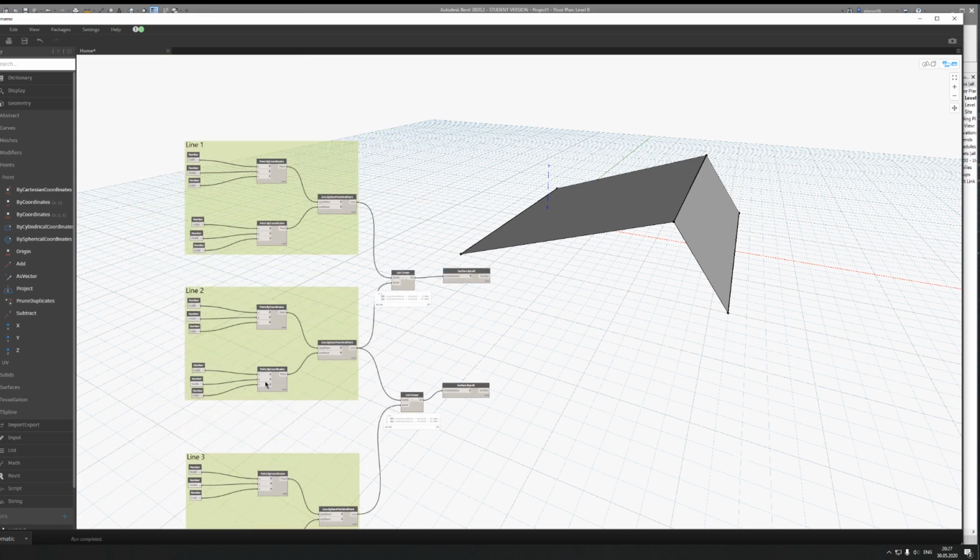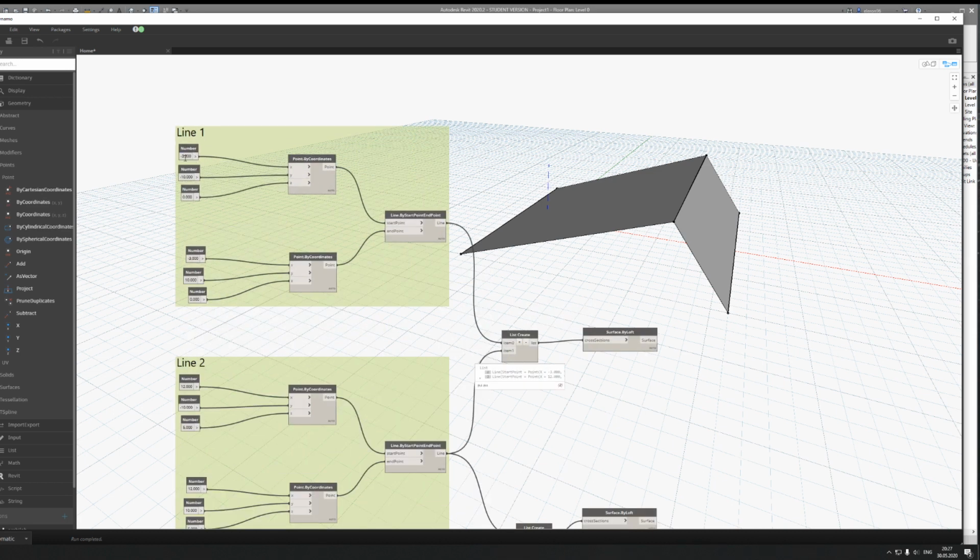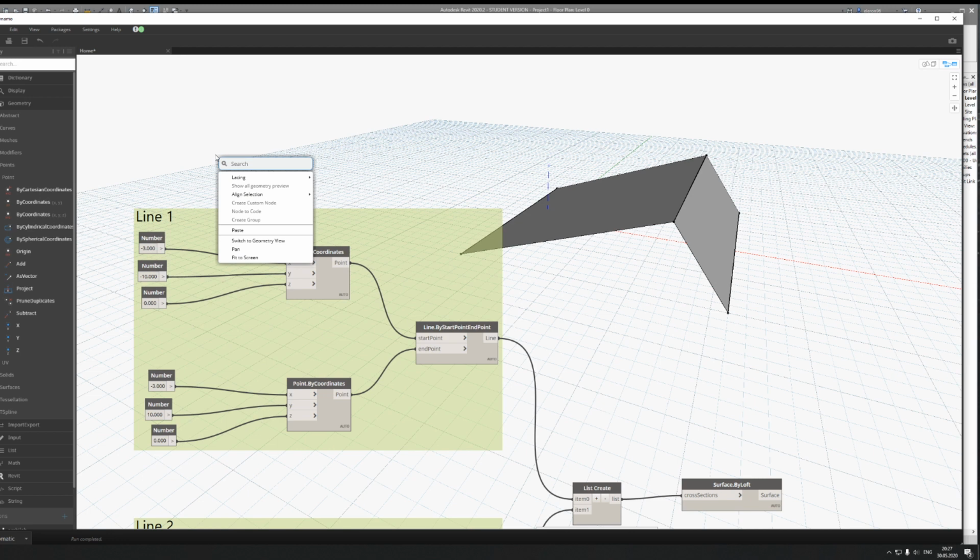And let's now talk about the slider, like one of my friends already talked about sliders. Because as you understand, it's really hard now to always change the numbers. You want to just play around with the numbers, right? So right click and let's write slider. You should understand we have two different sliders: the number slider and the integer slider.